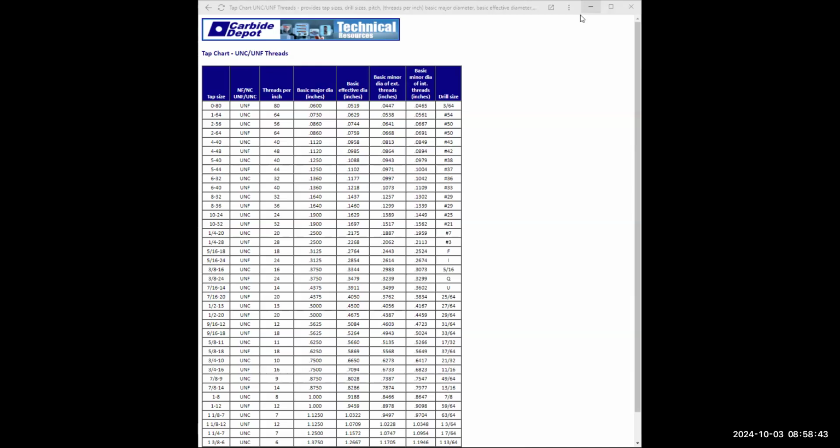So I'm going to erase this line. You can click on it and hit delete. I'm going to type in offset, enter, and I'm going to type in 0.125, enter, click on that line, and then indicate below, not above, but below. Click, enter. Click on this line, and we're going to drag this out all the way over to here. About right here. Click, enter.